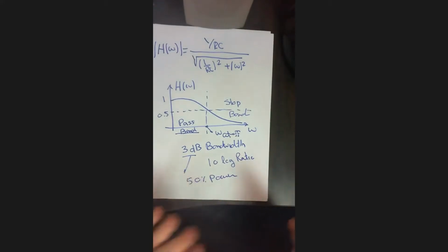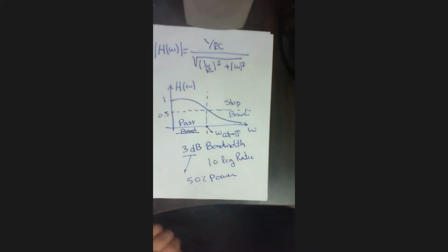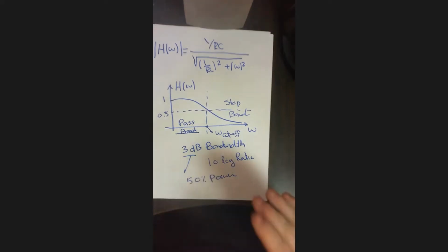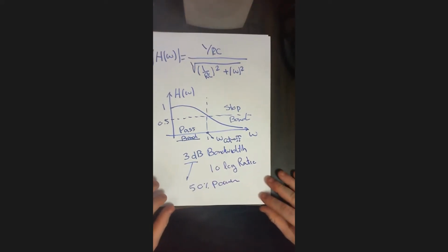So you can simply adjust your cutoff by calculating 50% of the maximum value on the frequency response. This is the simplest way we will usually use in order to estimate the cutoff frequency of any filter. Of course, you can do the same experiment with high pass filters, band pass filters, or band stop filters. All will be implemented in the same manner.